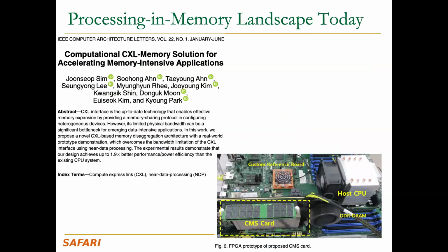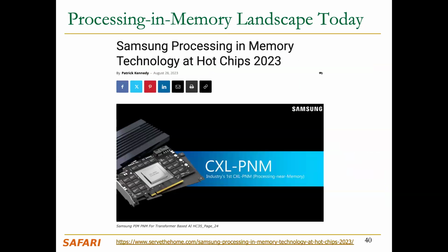With interfaces like Compute Express Link, which is an industry standard today, you could actually decouple processor and memory, and you can offload computation to the memory side. That's why you actually see other prototypes. Here, SK Hynix has an FPGA next to the memory, for example, and you can do processing in that FPGA that's next to the memory. Samsung has something similar also.